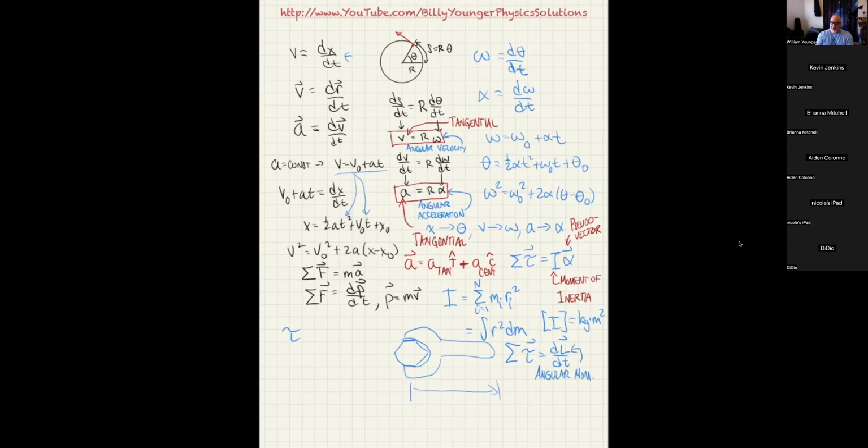Then I put a breaker bar on that, which was a hollow steel tube that was 4 feet long. So I basically stuck the end of the wrench in there so it had enough overlap and put another 4 foot on there. And I put all my weight on it and I still couldn't break it loose. So ultimately, and this is after trying impact wrenches and everything else, I ended up taking basically a wrench that was then attached to a breaker bar, which was 4 feet long.